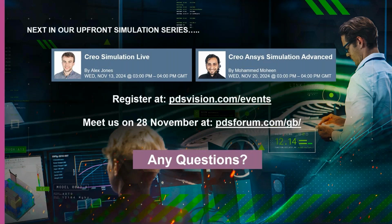We've had a question, Eddie, about using it for welds. Is that something that you would do with this, or would you use another tool set that we have? So the weld tool within Creo Simulate is for defining the connectivity between shells. For sheet metal parts, you can use it to connect them via perimeter welds, end welds, or spot welds.